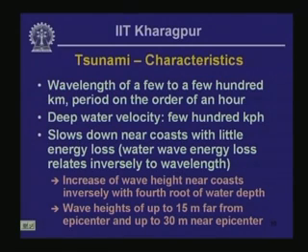The wave propagation velocity could be as large as maybe 900 kilometers per hour in very deep waters, and the velocity is going to slow down, because if you recall, the propagation velocity of a shallow water wave is proportional to the square root of g, the acceleration due to gravity, multiplied by the depth of water. So near the coast, the wave velocity is going to slow down.